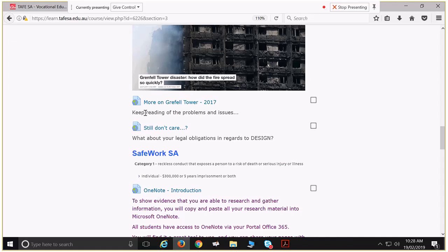There's a large residential building in central London that caught alight, and it was really quite tragic. A lot of people died, and basically it can very easily be traced back to the choice of cladding on the building. Yes, it was started by a refrigerator, but the way in which the fire spread was as a result of the cladding chosen for the renovation of the building. That's aluminium sandwich panel cladding, and that story just keeps evolving. So Grenfell Tower has not happened in isolation.